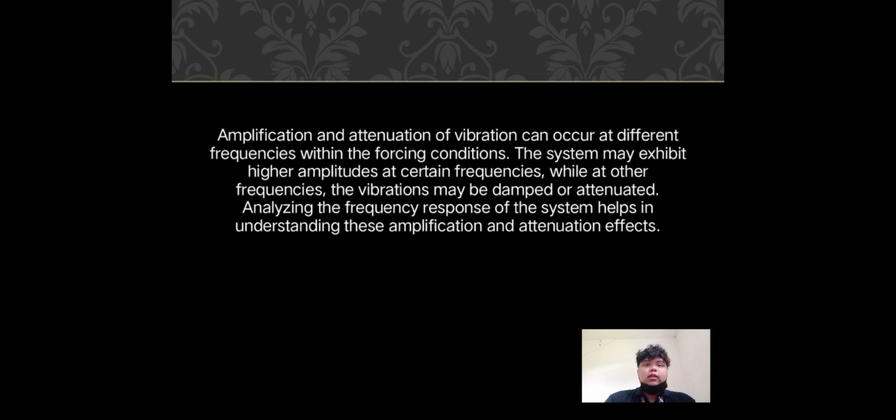By analyzing the recorded data, engineers can determine the system's natural frequencies, mode shapes, and damping characteristics. They can also evaluate the frequency response of the suspension system to different types of excitation. This information helps in optimizing the suspension design to provide better ride comfort, stability, and control.